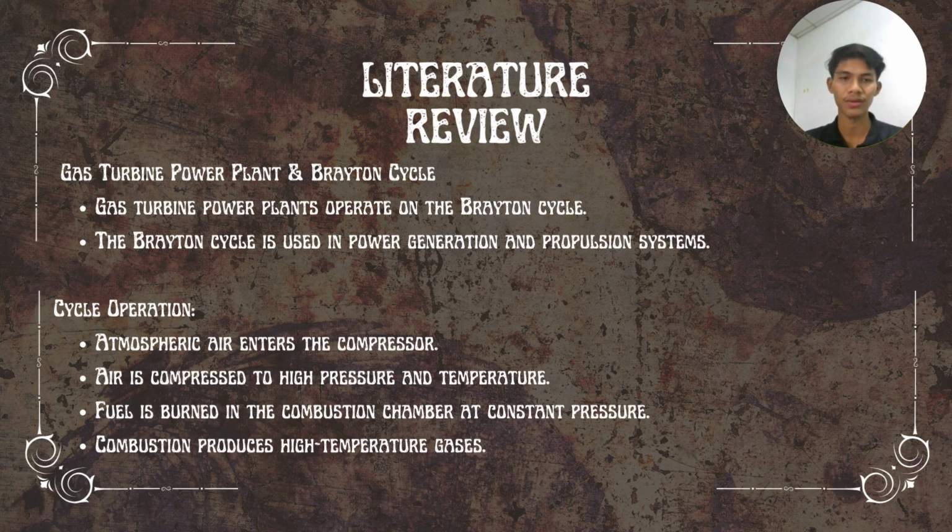After that, fuel is injected and burned in the combustion chamber at a constant pressure. This combustion process produces high temperature gas. These high energy gases are expanded through the turbine to produce mechanical work, which can be used to generate electricity. Overall, the Brayton cycle is known for its simplicity, reliability, and suitability for high power applications, making it an important reference for our project.